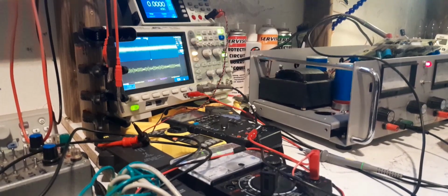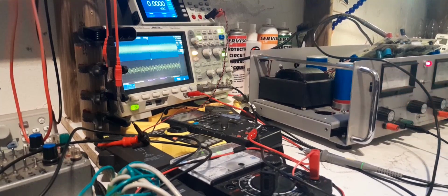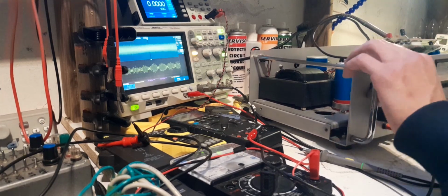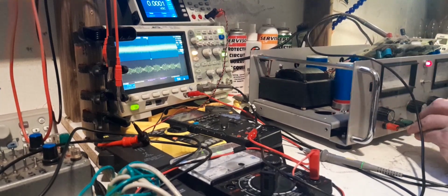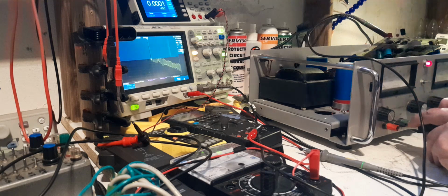Nothing's changed, right? And that's literally 100 nanofarads from the output to the input. And that's a ridiculous value. You know how much that's going to slow it down? That's unacceptable. Like, by no means is that in any realm acceptable. Let's actually have a look at what it does when we load it, just out of curiosity. Just goes absolutely ballistic.